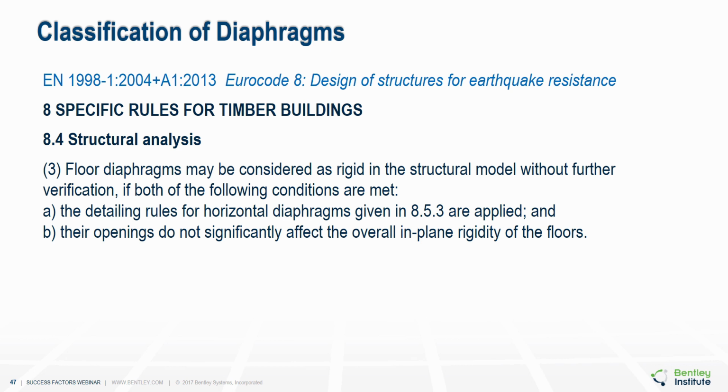The discussion on the Eurocode was brief. The references in the Eurocode are brief. And the intent was to point you to the applicable sections of the code so that you can study them more carefully. Again, any diaphragm can be analyzed as a semi-rigid diaphragm rather than turning to rules to determine if it needs to be rigid or flexible. Analytically, if you prefer to analyze the model as a semi-rigid diaphragm, that is certainly acceptable.